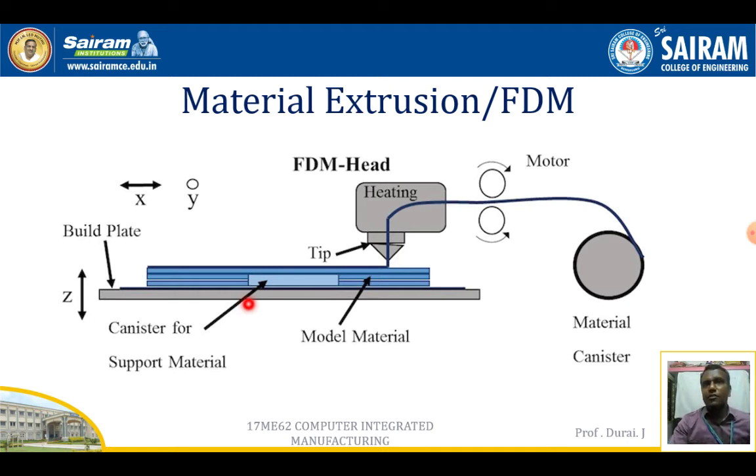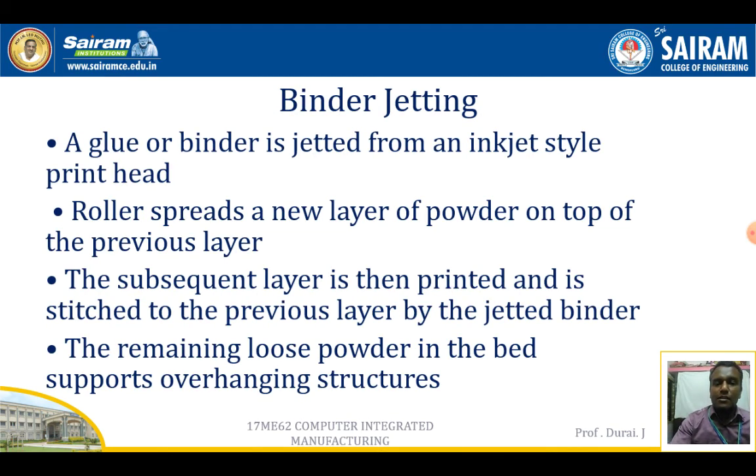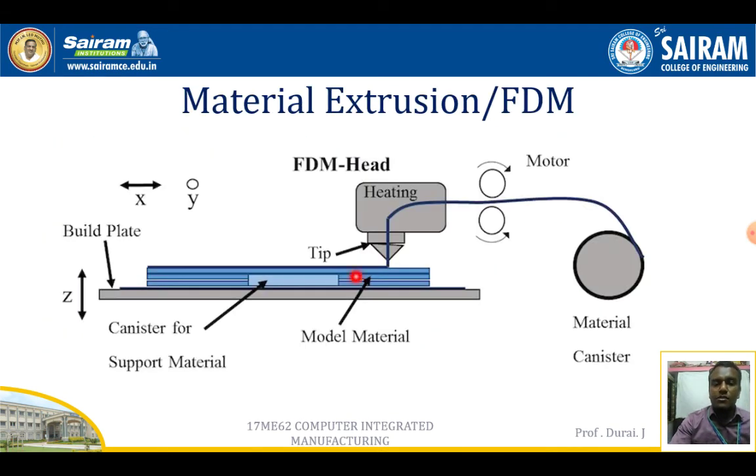In the material extrusion process, ABS plastics are readily available. The process has many factors, such as the nozzle shape, which influences the thickness of the layers. The material is fed into the nozzle at constant pressure, and the filament is constantly drawn into the nozzle.